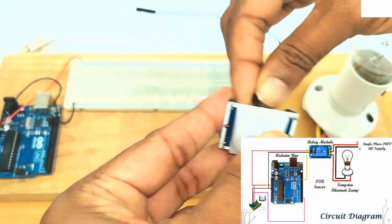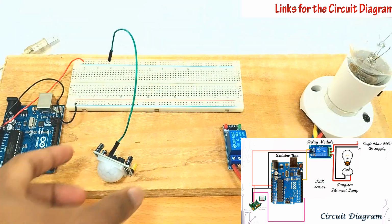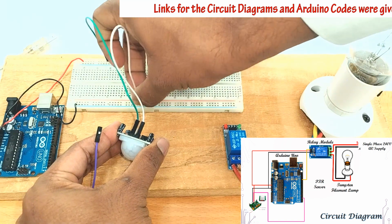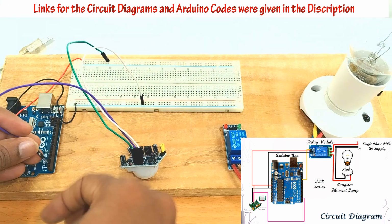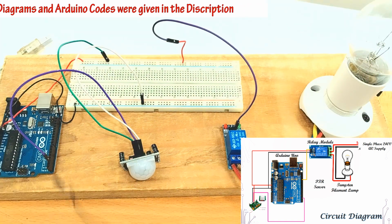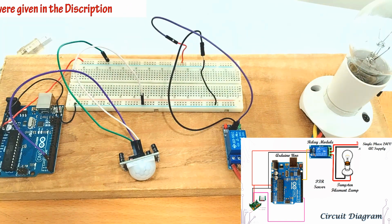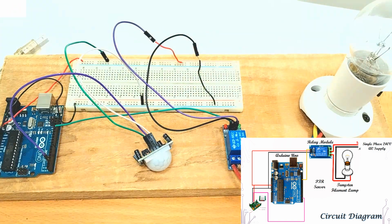So let us do the connection for this. This is the VCC pin, connect it with the VCC line, and this is the ground pin, connect it with the ground line of the breadboard, and the middle is the output. You need to connect it to pin number 2. Connect the VCC of the relay module to the 5 volt line, connect the ground of the relay module to the ground line, and connect the control pin of the relay module to pin number 13. Now all the connections are over.